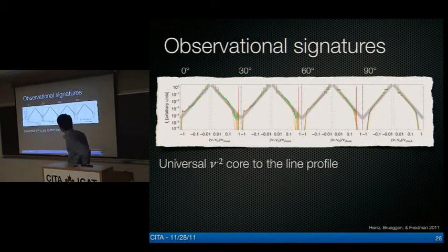And so this is what the velocity profile of this vortex ring does to a delta function. It smears out a delta function in this line profile over here. And so this is for different time steps of one simulation. And they basically look very, very similar to each other. Right? So there is what looks like, at least for this particular Mach number, a universal line profile you expect from this vortex ring that you get from shock bubble interaction.